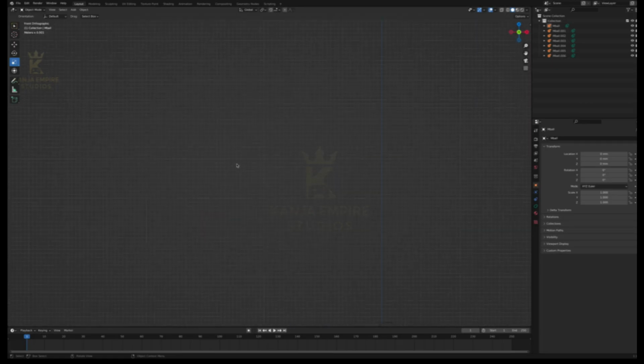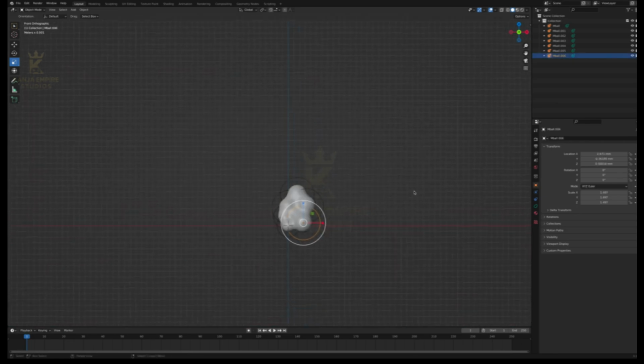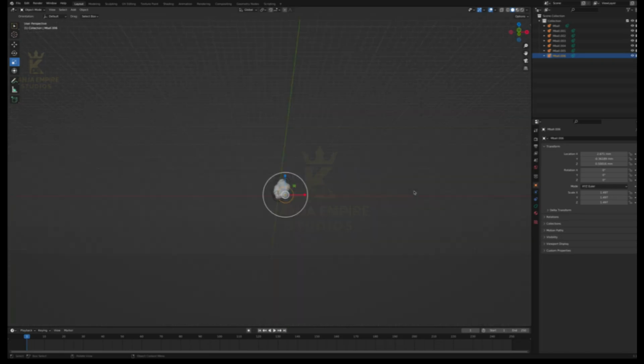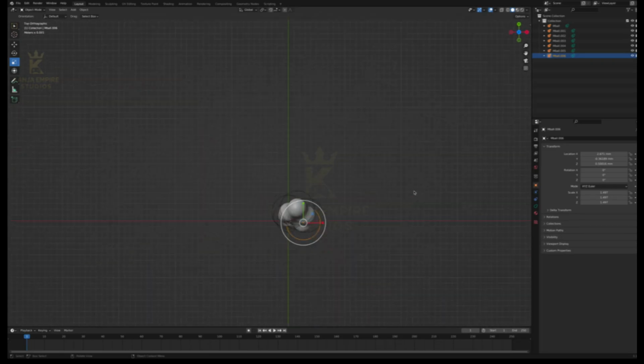That way, you could use some keyboard shortcuts for the view. For instance, let's see, select our object here. Let me go back to it. You could press 1 to go to the front view. You could press 7 to go to the top view. And you could just experiment around and press all the num keys to see the angle it goes at.